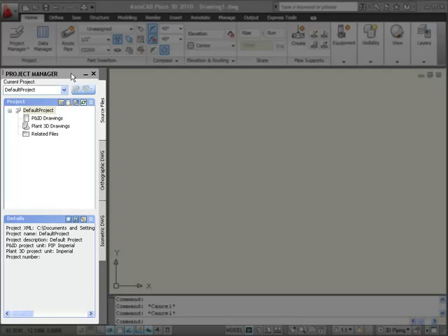The starting point for managing projects is, of course, the Project Manager. In the introductory video, I talked about how AutoCAD Plant 3D organizes drawings into projects and how the project controls the pipe specs available, allows piping connections to cross drawings, and allows project-wide data viewing, exporting, and importing. The project also controls the annotation styles available, the data fields for each component type, customizations, the organization of objects in Data Manager, and so on.